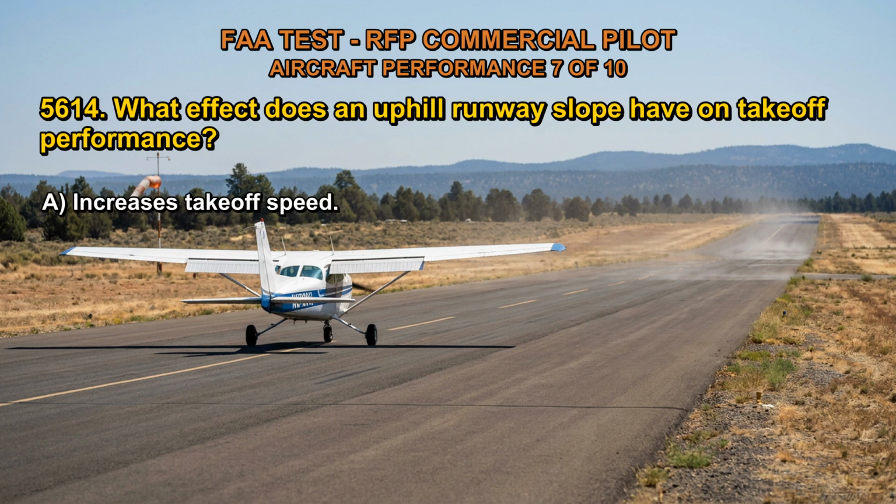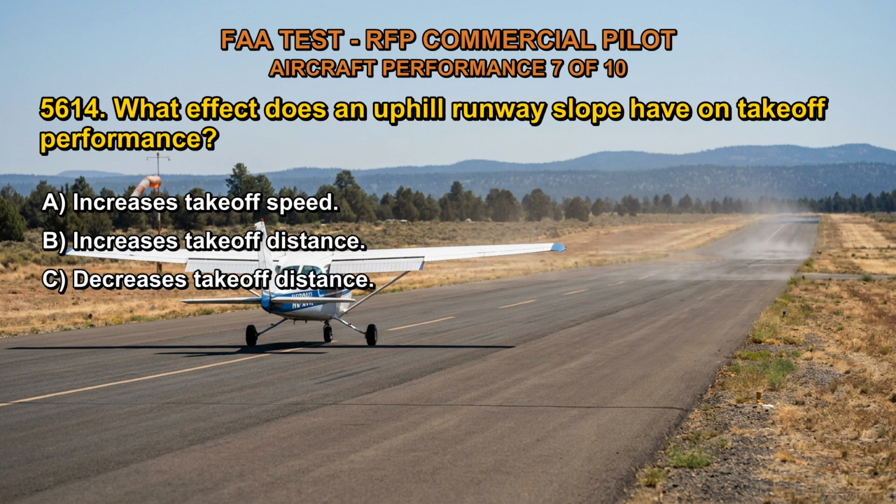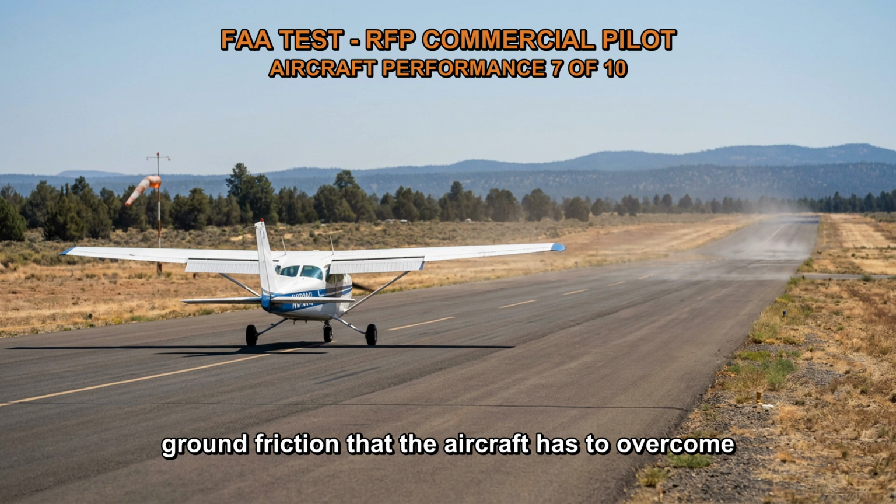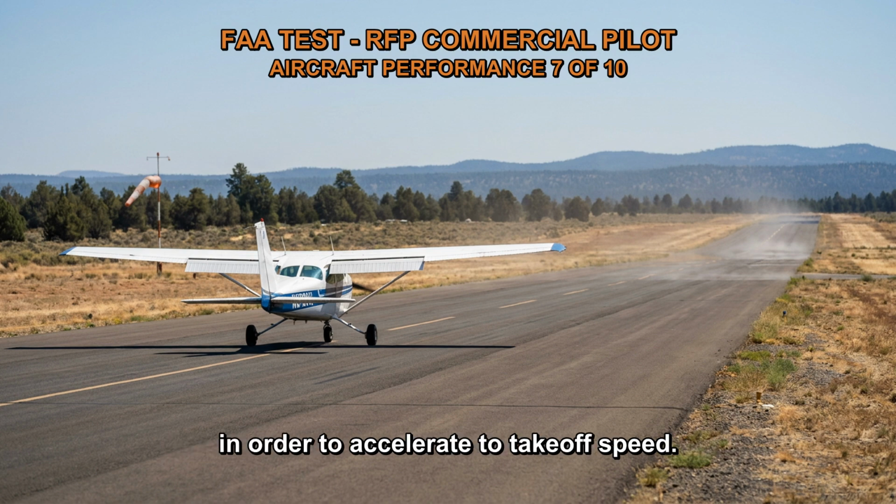5614. What effect does an uphill runway slope have on takeoff performance? A. Increases takeoff speed. B. Increases takeoff distance. C. Decreases takeoff distance. The correct answer is B. An uphill runway slope increases the amount of ground friction that the aircraft has to overcome in order to accelerate to takeoff speed.